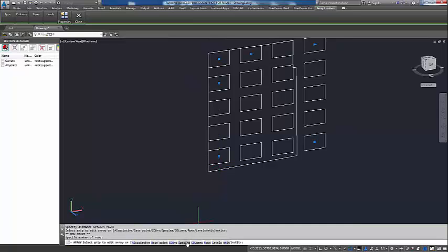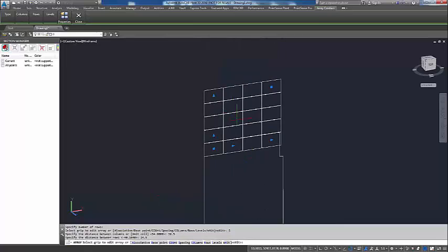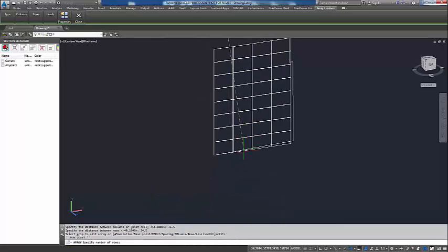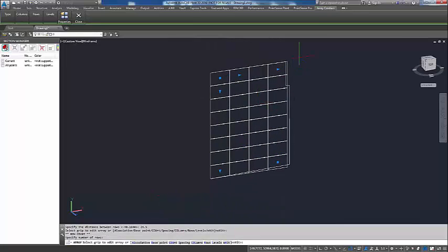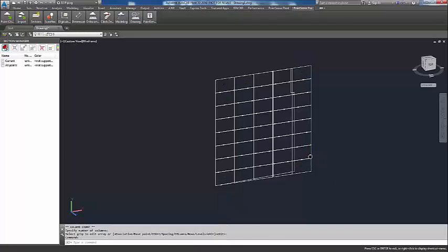We can specify how many panels we want going downward. Also our spacing down here at the bottom in CAD, we'll say that we'll do 36.5 to get a half-inch panel gap in our columns, and then we'll repeat the same for our rows. So 24.5. And since that went in a positive direction, we'll just drag this downward here. We'll drag this over just one more row to the right, and then we'll just hit spacebar to complete the array.